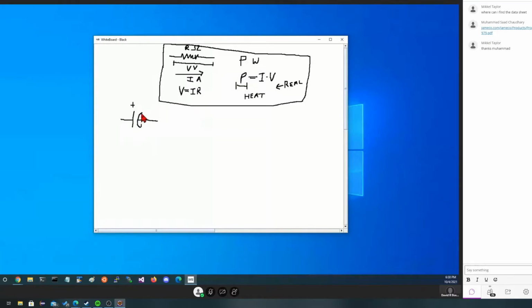Now, if I push these two plates closer and closer together, so that I have basically some metal, some insulation, and some metal, and then I provide high voltage relative to low voltage across it, and I wait 5 minutes and I look at it, I'll see no current passing through the device. It will appear to be infinite resistance. No matter how close together I get these, unless I put enough voltage to break down the insulation, which could happen, but the closer I get, as long as I keep the voltage under control, no current will pass,